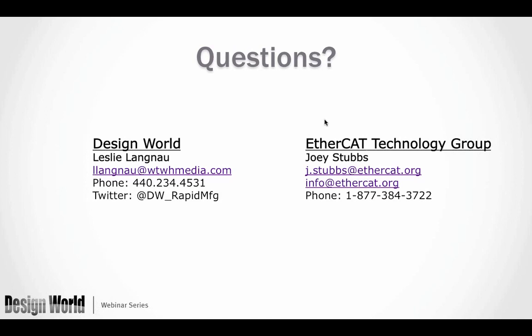You can create a network with your digital output modules, and as long as they have a good filter time, so typically this I/O is more tailored for EtherCAT these days, so there's I/O out there that has 1 microsecond filter times, digital modules. You can throw those on an oscilloscope and also check out the performance of EtherCAT. But it's not the frame jitter. That's the important thing with EtherCAT. We allow the frames, we expect the frames to jitter coming from a standard PC, a standard controller with a regular Ethernet port on it.